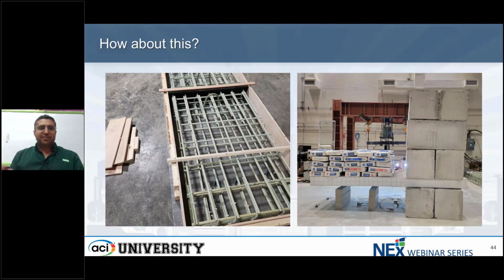So now let's look at other applications. We have done a cantilever test in-house, a balcony cantilever with 8 or 9 feet of cantilever, and we loaded it to the ultimate. This is the ultimate load that the designer said, at that load, this balcony would fail with steel, would yield and deform and would literally hit the floor. We loaded the same thing with MSD bar fiberglass, and we loaded to 1.8 tons. I forget the pressure we put there in kilopascal. I believe 196 pounds per square foot. That's how much load we put there. And if you draw a line, you should be able to see a decent deflection at the end of this slab.